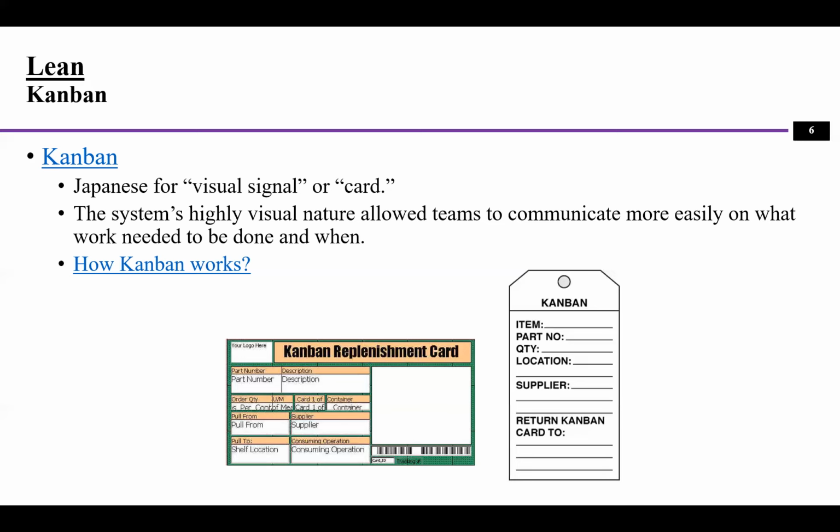What triggers the Kanban level going from 10 to 5 is actually your next process, because the next process receives the order saying that we need to make 5 parts, and then the next process directly gets the finished parts from your process. You finish your parts and you have 10 in inventory, and then the next process directly gets these 5 parts from your inventory, and then he can start to make. So he does not have to wait a long time until you finish all of those. He can get directly from the inventory.